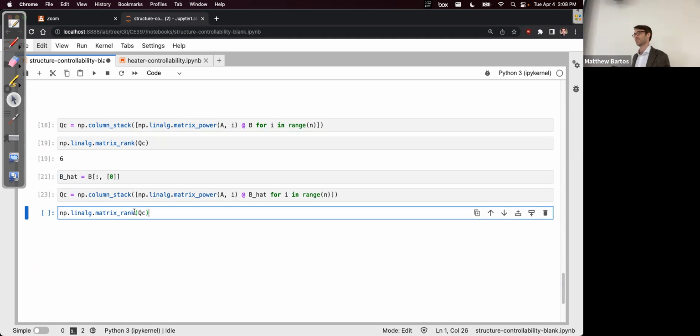First of all, does anyone want to change their bets? Who thinks the system's going to be controllable? So the definition is if any state can reach the origin, right? So equivalently, you can drive the system from the origin to any desired final state, which is 6-dimensional, right? But if it's to the origin, and it's an oscillator, then won't it always go to the origin, even if I just put in an input of 0? Like even with no actuators, would it not be controllable? That's a good point. I'll have to think about that. That sounds correct, though. In terms of reachability, you also have to be able to drive the system from an initial state at the origin to any desired final state. So stability doesn't necessarily imply that.